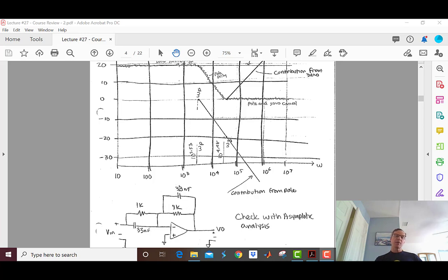So that means they're not in the circuit. So the gain is going to be equal to -9 over 1. It's just Z2 over Z1, right? And this clump became just the resistor, and this clump just became this resistor.